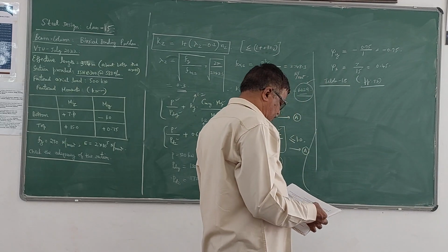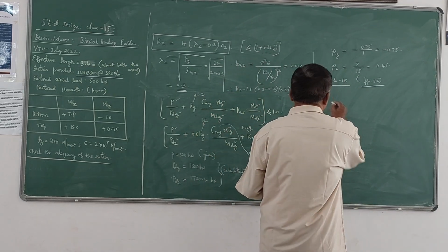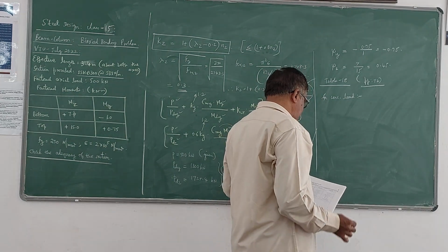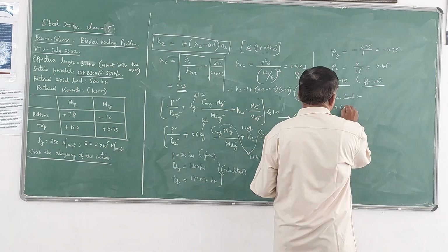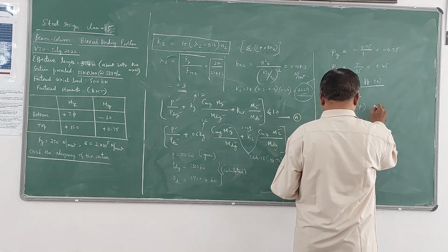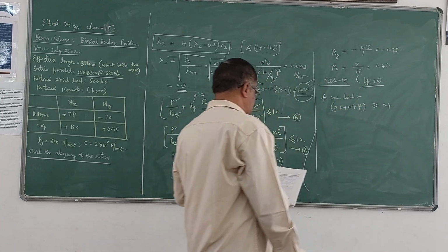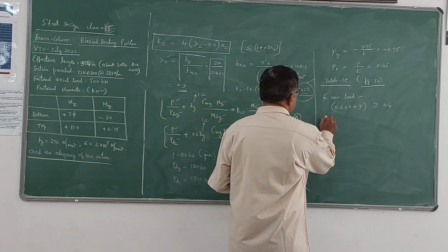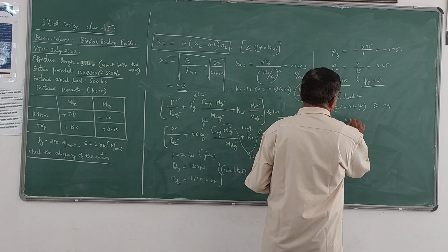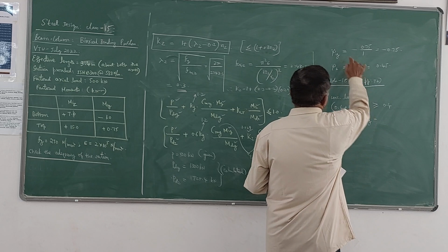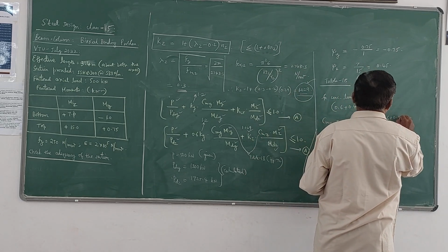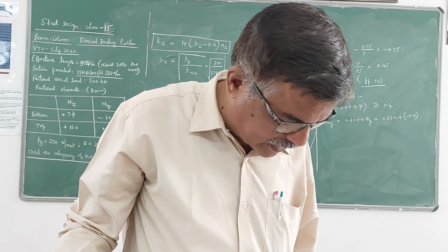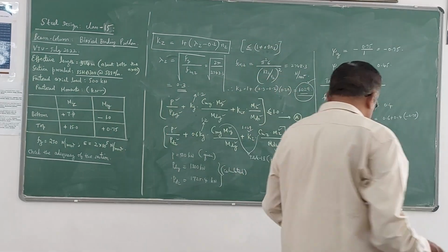For concentrated load we have to take, because the axial load is a concentrated load, 0.6 plus 0.4 psi, and it should be greater than or equal to 0.4. This is the condition under concentrated load as well as uniform loading. So the value of CMY I can take now is 0.6 plus 0.4 into psi y, which comes out to be 0.6 plus 0.4 into minus 0.75. Of course, if you simplify that, you will get the CMY value as 0.3.